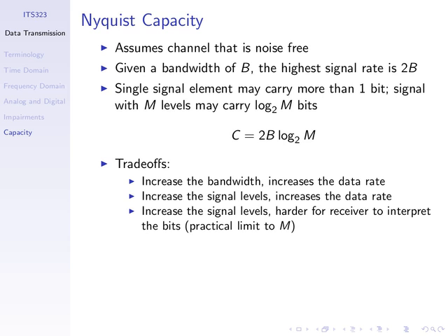For some type of data, we have to put the FC that's suitable for that data. So my voice, the original data, has frequency from 0 up to 4 kilohertz. But if I want to send it across the microphone system, it transmits at, say, 900 megahertz, a different frequency from my voice. So we actually have to shift that analog data to a different center frequency. And the result is that we get some signal with a center frequency and some bandwidth.